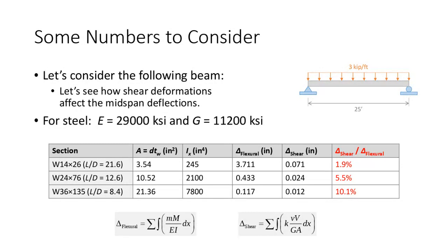So I'm not making you do that, but this is just a view into the real world. If you ever have a beam that you're designing or analyzing and it's really deep in comparison to its span length, you need to consider shear deformations. RISA does this automatically, and we'll get into that on Wednesday.